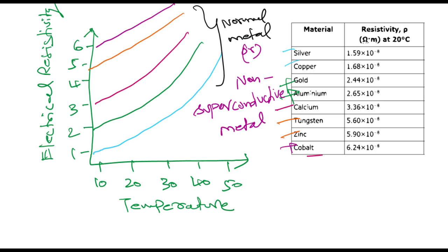However, resistivity is a material property of the conductor. Actually, it depends only on the temperature of the conductor and not on the length, density, or cross-sectional area of the material. As a result, increasing the length increases the resistance of the body but not the resistivity. So simply we can see the graph explaining the length, density, and the cross-sectional area of the material.